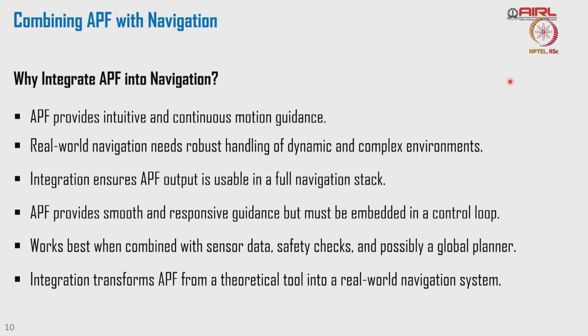Integrating APF into navigation makes it useful for the full navigational stack. Otherwise, we will be talking about point to point. I generate a path based on the map where I know where the obstacles were when I visited last time. But the environment is not static, it is dynamic. The obstacles move, right? How am I going to navigate in that particular map? That is where I need this.